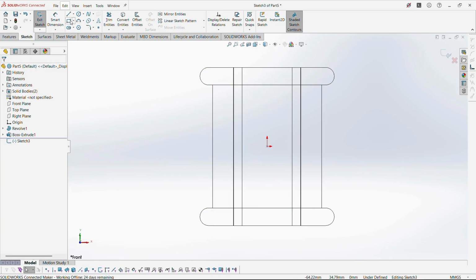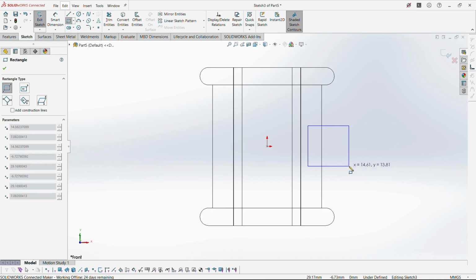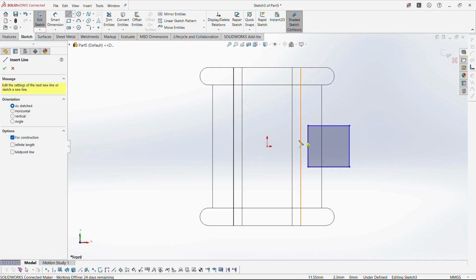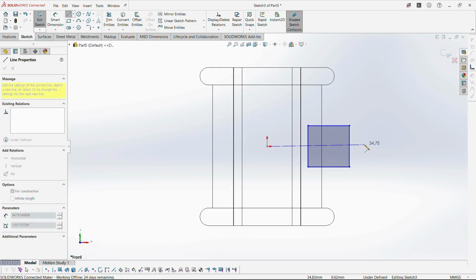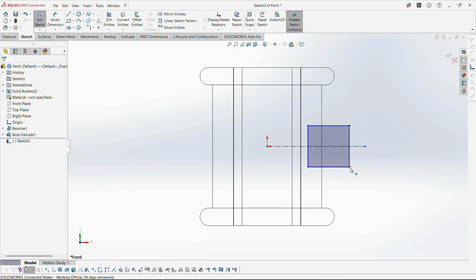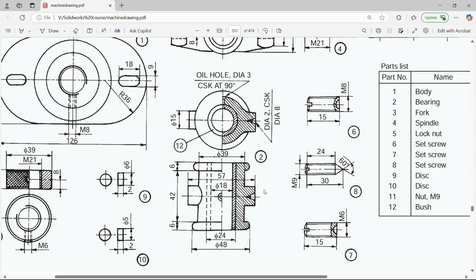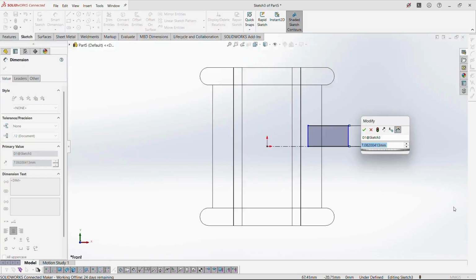Because it is easy to view the inner area, and drawing the profile at the right portions is also perfectly easy. Let's draw a horizontal center line. We just need to coincide this point at this area. Afterwards, give the dimensions for this portion as 15 mm. Then give 7.5 mm.